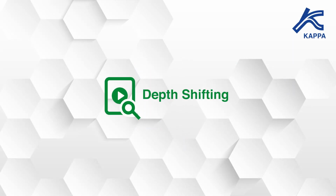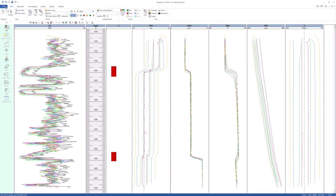Depth shifting. In this session, we will learn how to depth shift passes with respect to a reference channel. For this, we will use the Shift option found in the Depth section of the Edit QA/QC ribbon.